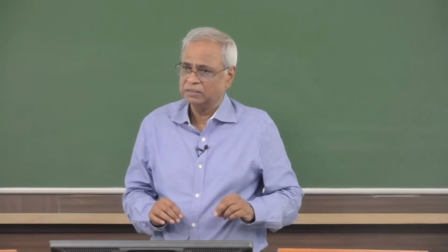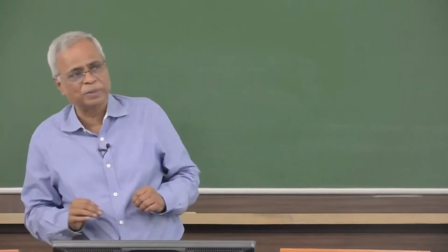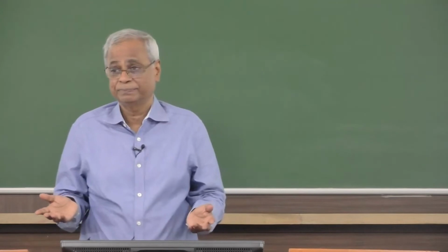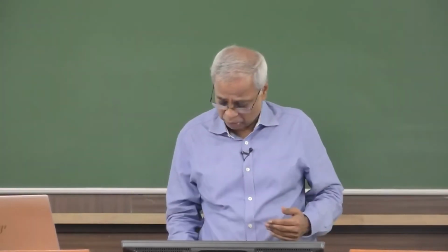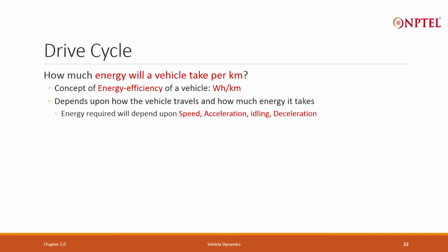Energy efficiency is defined in terms of watt hour per kilometer. That depends on the vehicle design, but it does not depend only on the vehicle design. It also depends on how the vehicle travels. When you do the measurement, what is the speed at which it travels? Remember that when it travels at higher speed, you require larger power, which means larger energy is consumed. So, you cannot talk about energy efficiency or watt hour per kilometer at all speeds, it will be different.